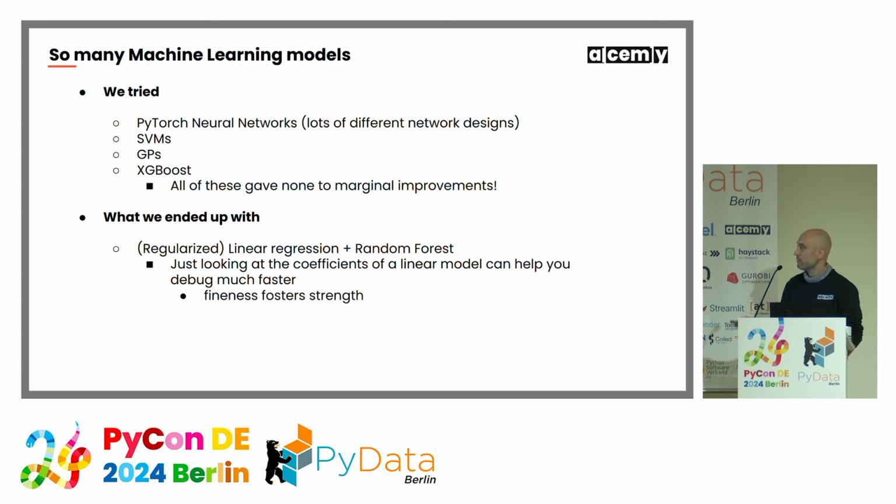So if we can see, for example, that fineness fosters strength, right, because we steer with fineness, this should actually come out in our model. Then we know that we can actually deploy this and use this. If that wasn't the case, we would be kind of screwed. Or stuff that is, for example, known to process engineers in the cement industry, like titanium dioxide reduces strength, or your actual clinker composition can increase the strength, and that kind of stuff. That's pretty neat.